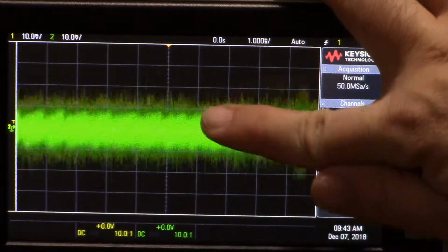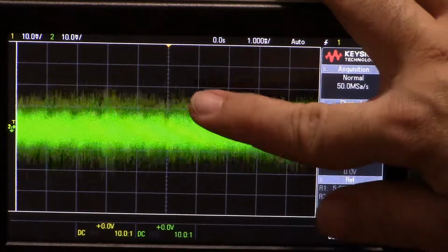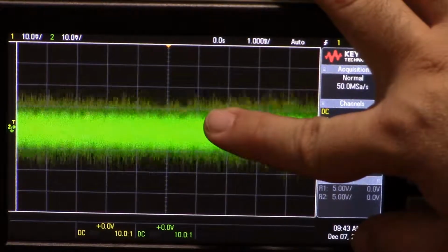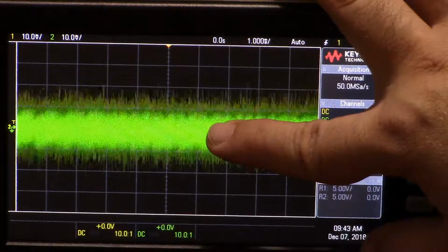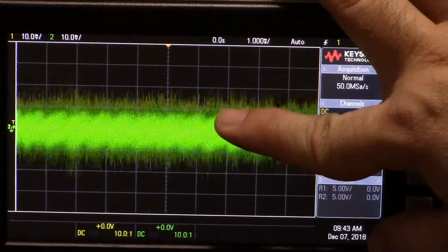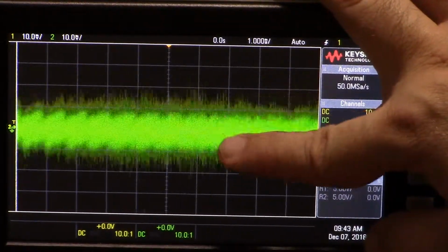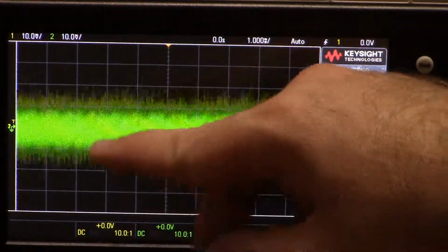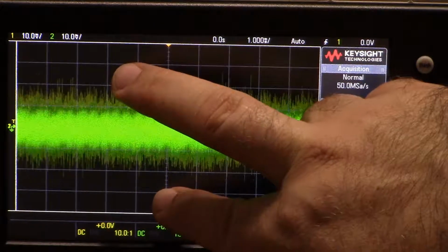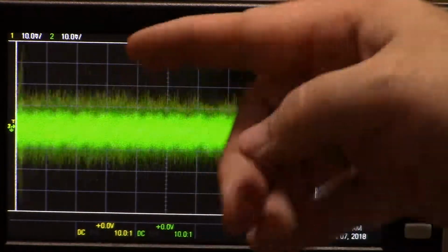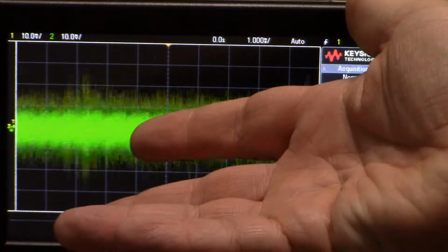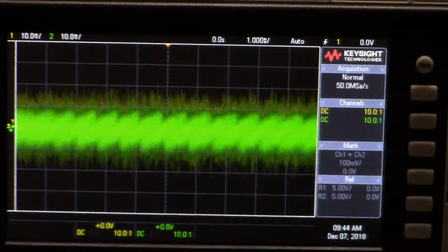That's not terrible. And keep in mind, I'm putting this through a breadboard. The vast majority of this noise is those breadboard wires acting as antennae. If you have a nice speaker wire that's a little better insulated, or even better, you're doing some twisted pair thing with high fidelity audio cables or whatever, this is the noise that's getting rid of. But it's like, what? 10, 20, 40 to 50 to 60 even millivolts peak to peak compared to the hundreds of millivolts. So signal to noise ratio at least 1 to 10, or I guess 10 to 1 signal to noise. That's fine. Probably won't be able to hear that too much. But in any case, that's the noise.